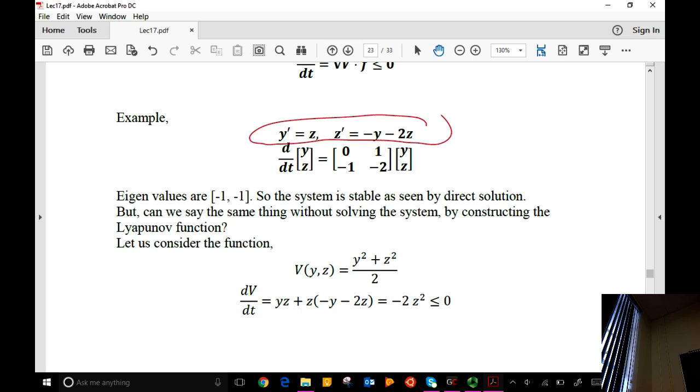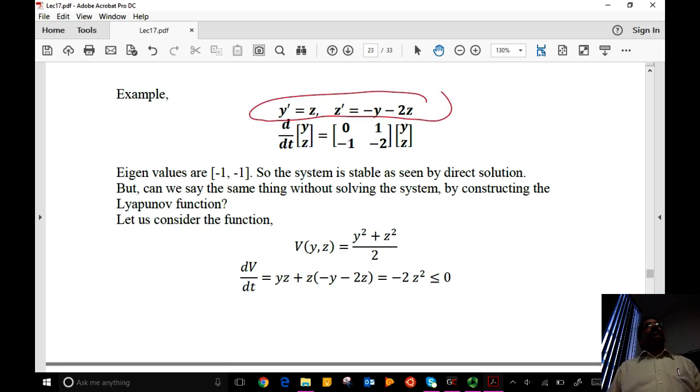And of course, you can verify in this case by solving for the eigenvalues. That's the power of these qualitative methods. But the challenge is in coming up with the correct function for V. So for real nonlinear problems, how people approach this is they will take some function and identify the region in the state space in which these conditions are satisfied, and call that region the region of stability, region of attraction. If your initial condition lies anywhere within that, you will be attracted to that steady state, around that steady state.